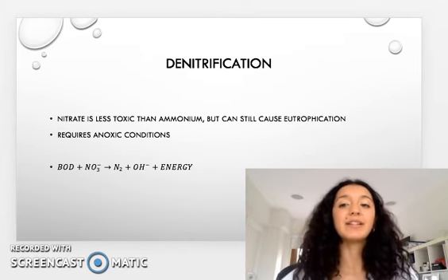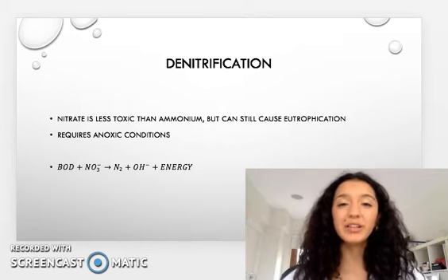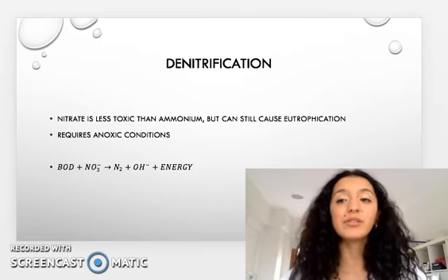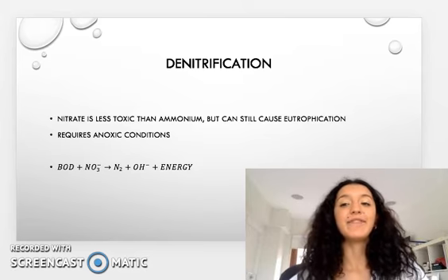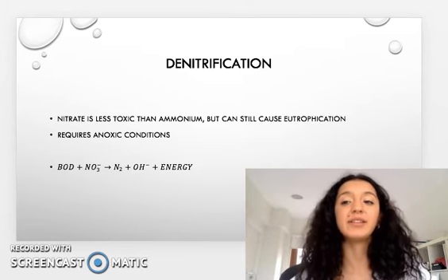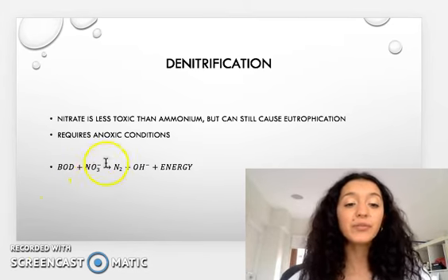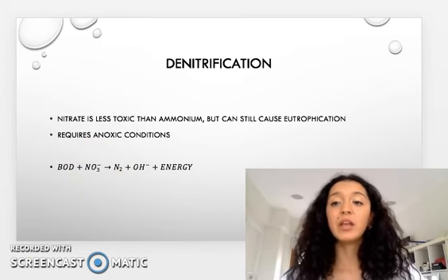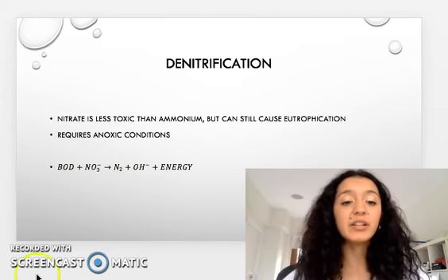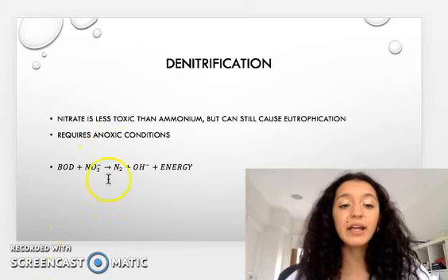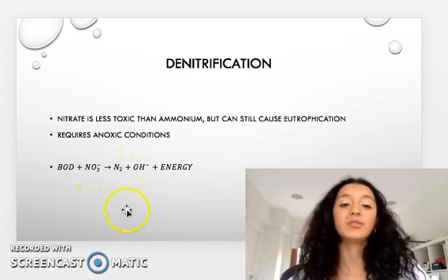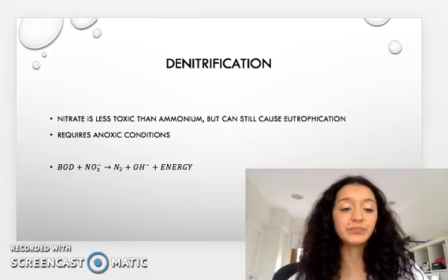This is where bacteria are used, which would normally feed on oxygen, but when they're deprived of oxygen, they feed on other compounds such as nitrates, where they strip off the 3 oxygen atoms. As you can see from this equation, the nitrogen will bubble off as nitrogen gas, and the hydroxide will also help balance the pH.